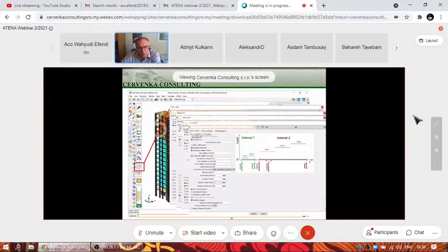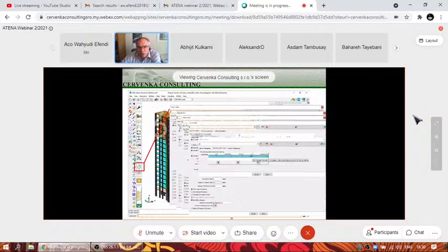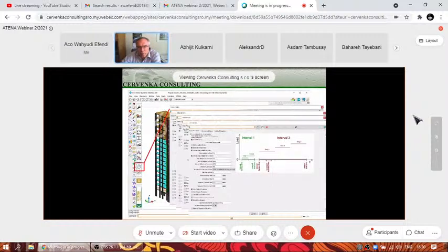So this is an 18-story building, which is subjected to an accelerogram. And here we define basically the time of the accelerogram, which is from 2 seconds to 12 seconds. And in this ground accelerogram option, we can find an input file containing this accelerogram.